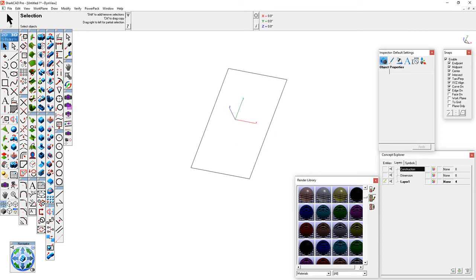And to make a 3D object, you just pick extrude solid, this one here, and I dragged that one off of this one here, and it was that easy. Just drag it off and then place it. And once you do it, right here's the blue distance, that's where you pick your distance, so we'll do 0.25 of an inch,